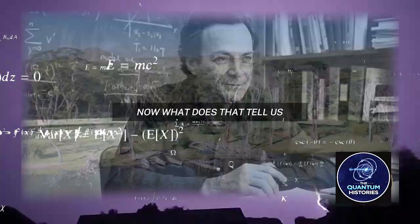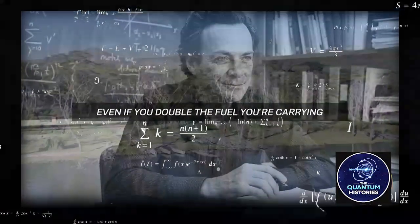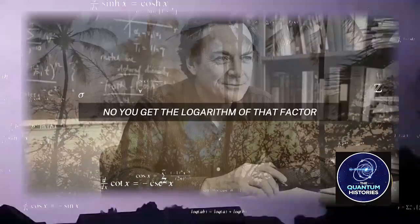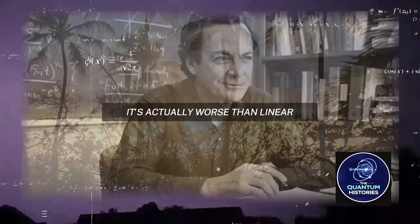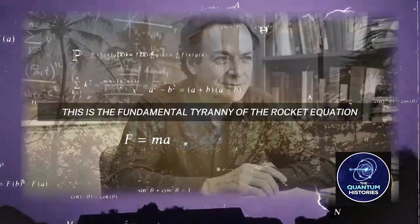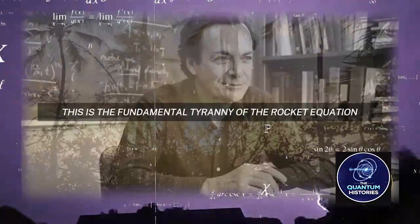Now, what does that tell us? It tells us that even if you double the fuel you're carrying, you don't double the velocity change. No, you get the logarithm of that factor. It's actually worse than linear. You get a logarithmic relationship. This is the fundamental tyranny of the rocket equation.